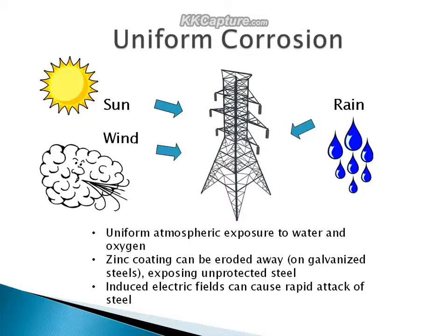In addition to the environmental effects, the ultra-high currents and voltages in the wires create induced electric fields away from the actual wire. This can set up electrical currents in the steel members, thereby accelerating the corrosion rates.